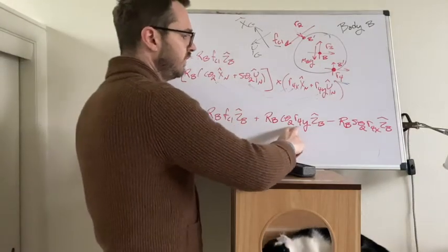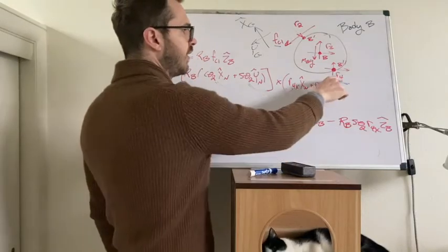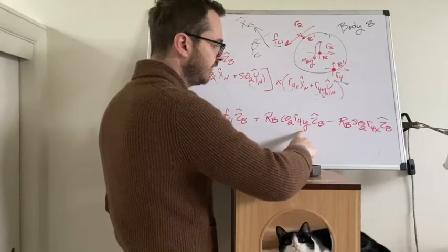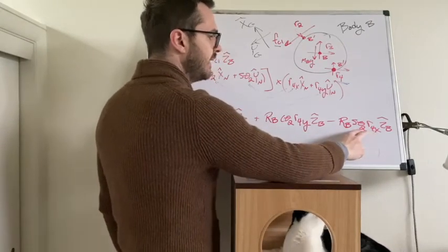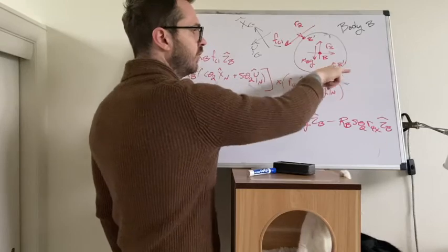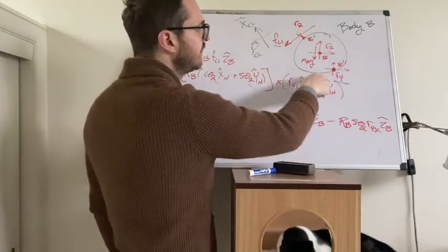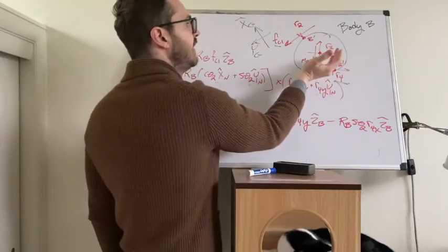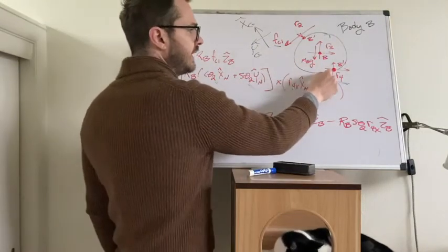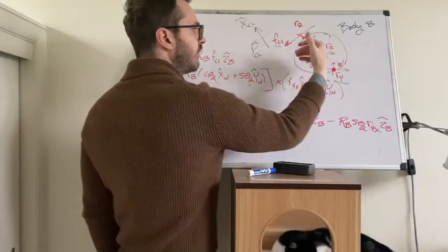Next, how should we understand these with the cosine and the sines? Well, R4 we're saying it is acting in the X hat in, this one's in the Y hat in, this one's in X hat in. If I were to take, as it's shown right now, and I were to say that R4X was a positive force, you can see that would also make the disc want to spin in a positive direction. Similarly, if R4Y is positive, that would want to push the disc in a positive direction. Now, what if the mounting location was not here, but on the other side of the disc? Then a force in the positive X in would create a negative moment.